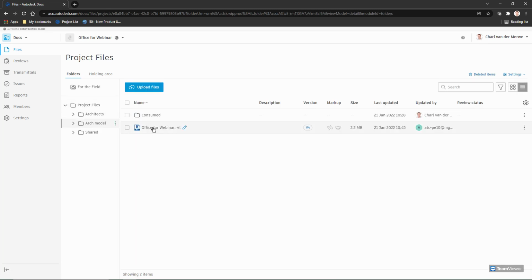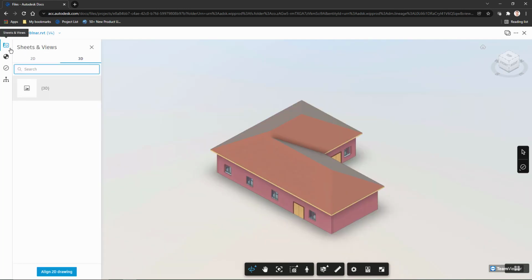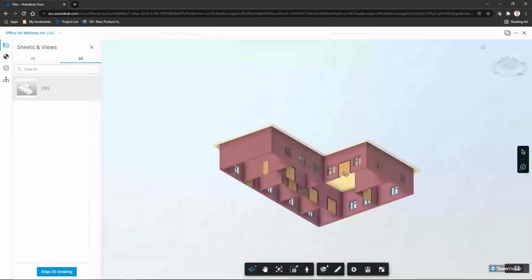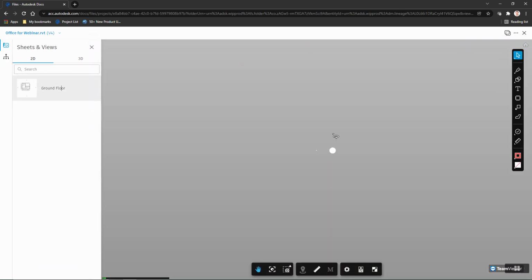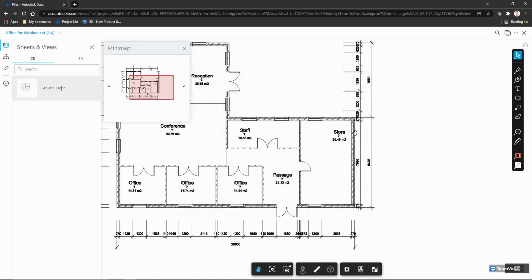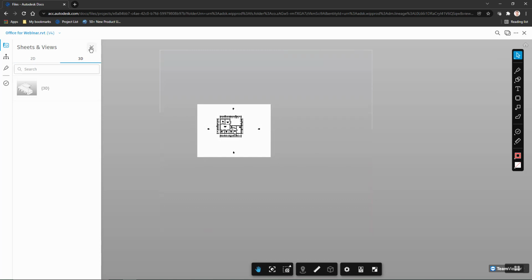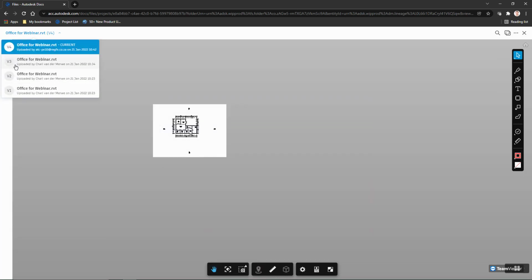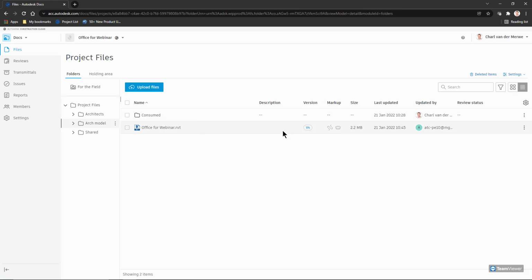All right, there's the architectural model folder. Yeah, I can view, or if I don't have Revit or BIM Collaborate Pro, I can access this published model. You will notice that if you go to the floor plan or whatever, you'll see that that has been enlarged, so that's fine. Right, so that's the viewer. So the version 4 is there. You can go to version 3, 2, and 1 and maybe compare them, etc. But I'm not going to do that at this point. I'll just close this for now. Right, you'll see version 4 there.